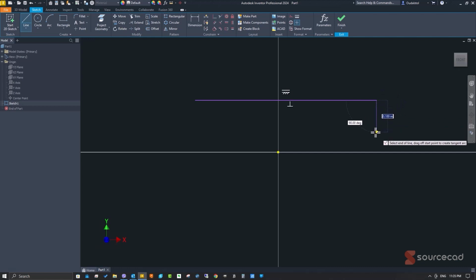And you might notice it's adding these 2D constraints. As I'm going straight down, it's going to suggest the upside down T. Before that, you might also notice a line and then a line again, two parallel lines, and then little squiggly lines underneath. That is the horizontal constraint. So the first line is set to horizontal. And as I get almost to 90, it's going to be a little magnetic, a snap to it, if you will, and it's going to show you the perpendicular symbol. So I can go down, and if I keep going, it's going to give me perpendicular again.